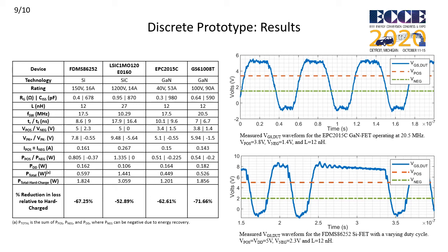Additionally, the lower right figure depicts the measured VGS gate signal with a varying pulse width duration, illustrating this resonant driver's suitability for use in topologies with diverse duty cycle requirements. A gradual VGS settling is also observed here. This effect is due to leakage and the charging of parasitics throughout the driver stage. Since this driver is high impedance while holding, leakage results in a lower bound being placed on switching frequency, further highlighting the importance of non-ideal element considerations.